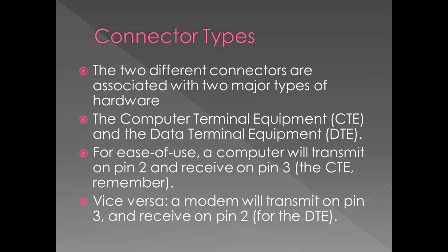The two different connections are associated with two major types of hardware: Data Terminal Equipment, DTE, and Data Communication Equipment, DCE. For ease of use, a computer will transmit on pin 2 and receive on pin 3.